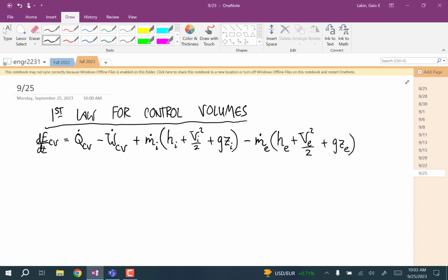And we're almost never going to use that full form. Maybe never. But the way I want you to go, get used to starting with that full form and then just think, why can I cancel this? Why can I cancel this? I'm going to tell you some standard simplifications, but even when you use these devices, the questions are going to vary what things you can set to 0, what things you can assume go away, that kind of stuff. So I want you to get in the habit of starting with this and then thinking, why can I cancel Q dot for this? Why can I cancel this?